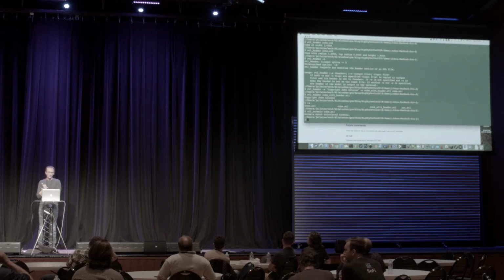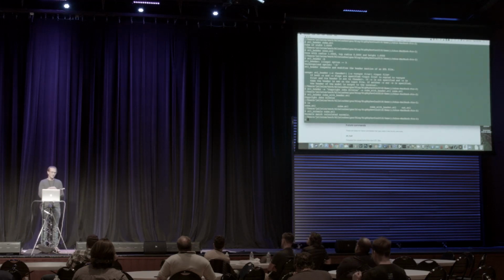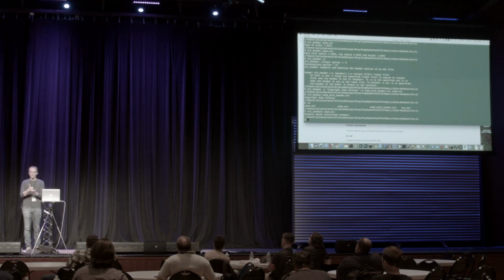But not all software uses that normal. Some software ignores that completely, and bases it entirely on how the points were oriented or laid out, like the order they were specified. The most common rule is to use the right-hand rule. If you curl your fingers around in the order that the points were listed, your thumb points in the direction of that normal.